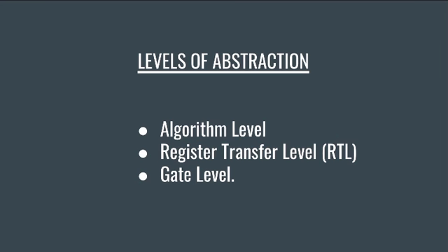In terms of timing, the differences between these three are as follows. A pure algorithm consists of a set of instructions that are executed in sequence to perform some task. Hence it has neither clock nor detailed delays. The VHDL input may have to be constructed in some artificial way for some synthesis tools, perhaps through the presence of an algorithm clock. The operations in the VHDL code can then be synchronized to this clock. The functions and states are the main elements in this algorithm level.